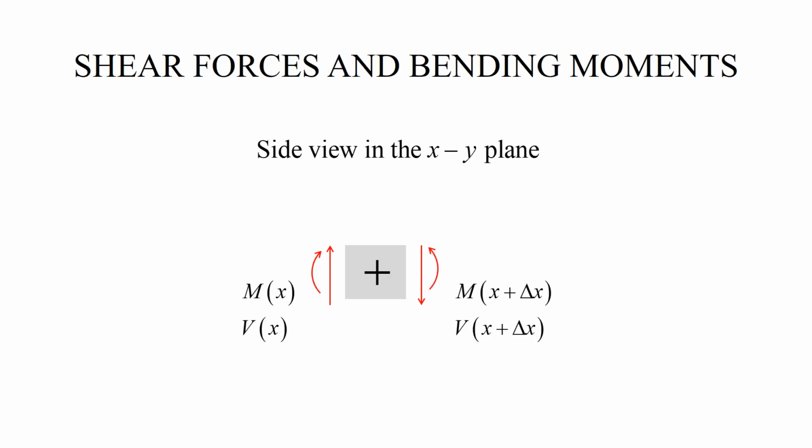We will rely on the standard convention for the internal forces. So the bending moment and the shear forces are shown on this infinitesimal element of length delta x, and the entire picture is in the xy plane.